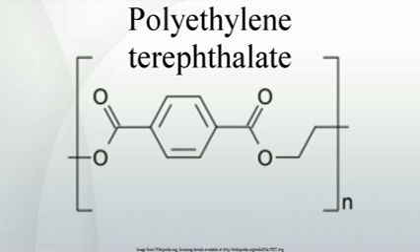Dimethyl terephthalate process. In the dimethyl terephthalate process, this compound and excess ethylene glycol are reacted in the melted state at 150 to 200 DEGC with a basic catalyst. Methanol, CH3OH, is removed by distillation to drive the reaction forward. Excess ethylene glycol is distilled off at higher temperature with the aid of vacuum. The second transesterification step proceeds at 270 to 280 DEGC, with continuous distillation of ethylene glycol as well. The reactions are idealized as follows.